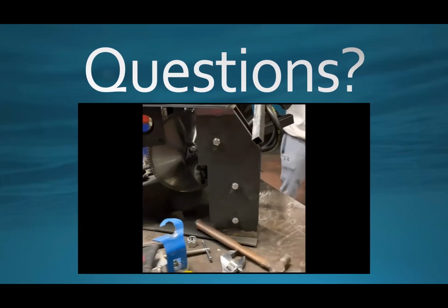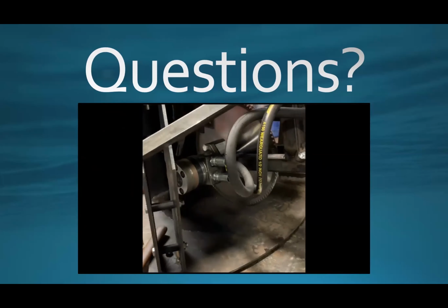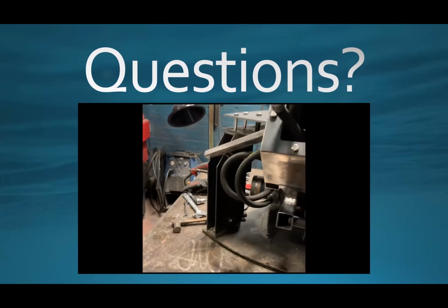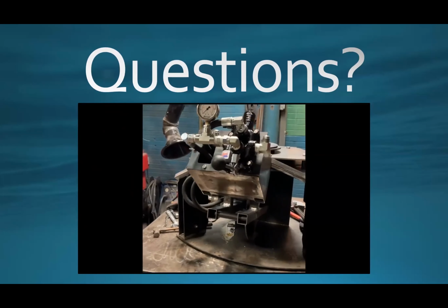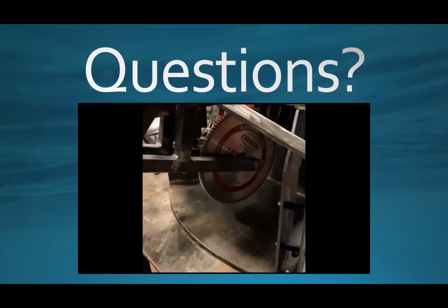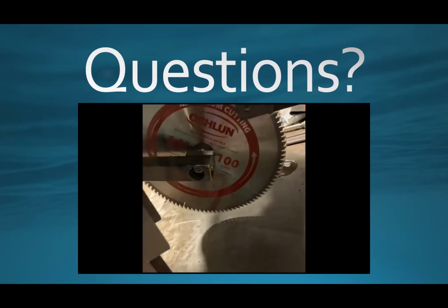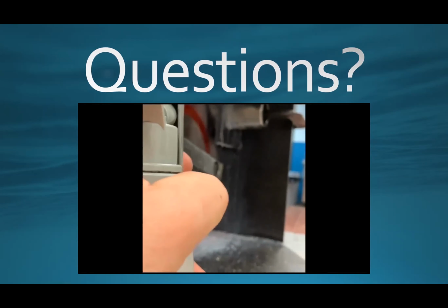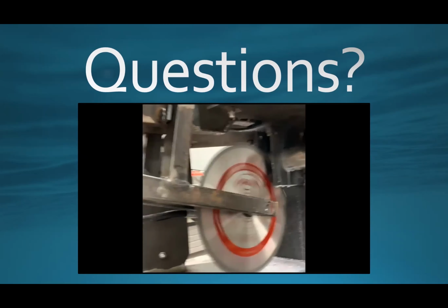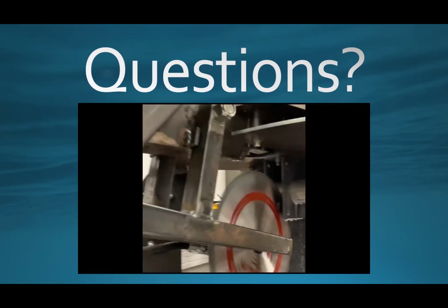Some of the things that you asked around how does hydrostatic head affect the tool? At OneSubsea, we're going to actually put the tool in a hyperbaric chamber to simulate how the tool responds at depth, which obviously you can't do in a university setting, but we can in a production setting. And then we also drop test the tool to represent, hey, what happens if the ROV drops the tool? How will the tool break? So those are some of the things that are different from a university setting to production.